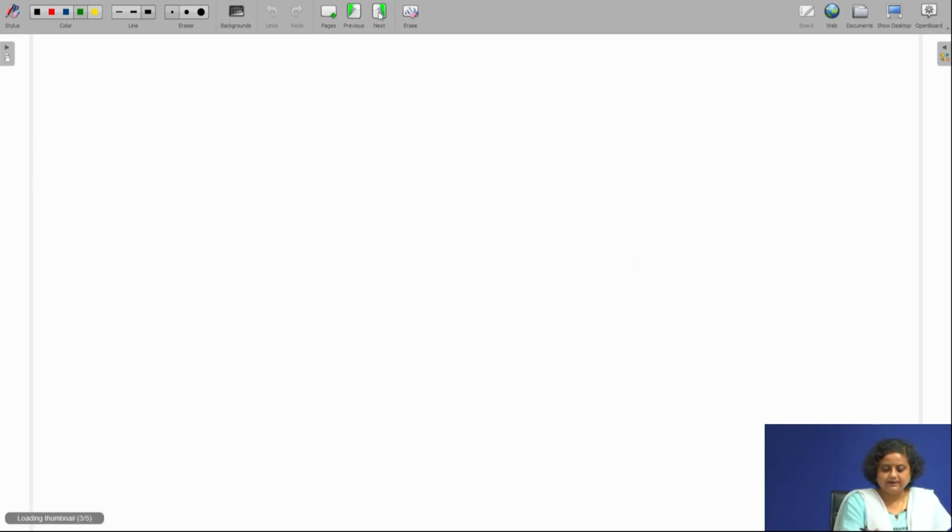So, let me write this down as Q(r+1) minus Q(r) is going to be minus Sy by Ixx into Br into Yr. So, this is the expression that we have. Now, the first thing that we have to do is to find out Ixx.